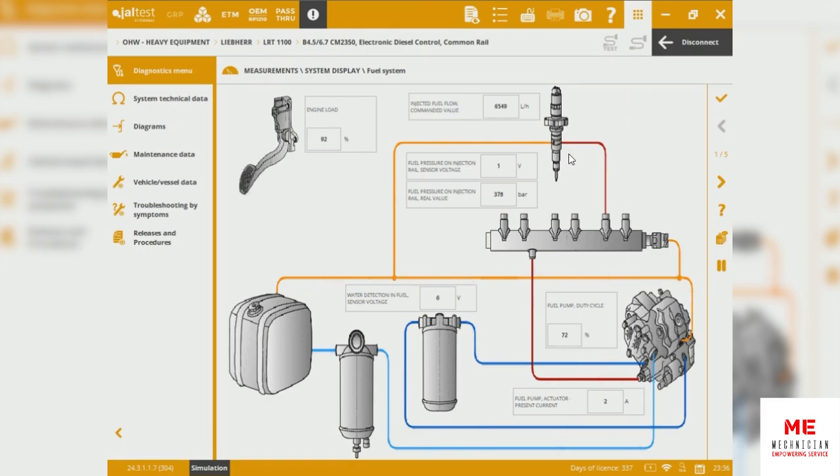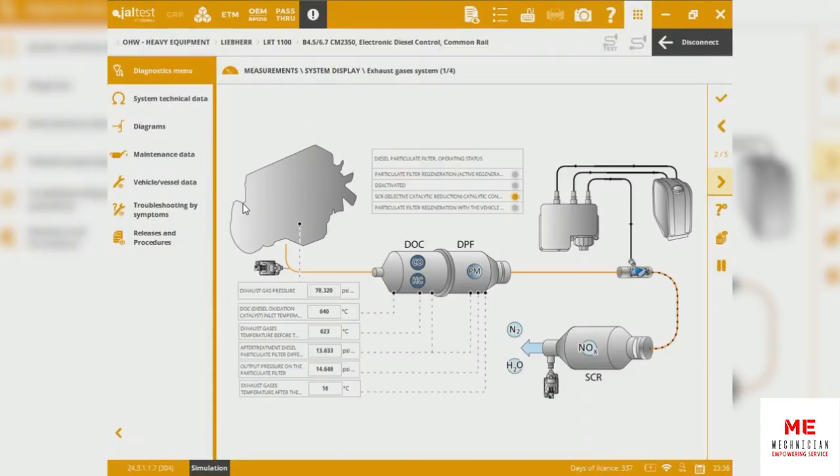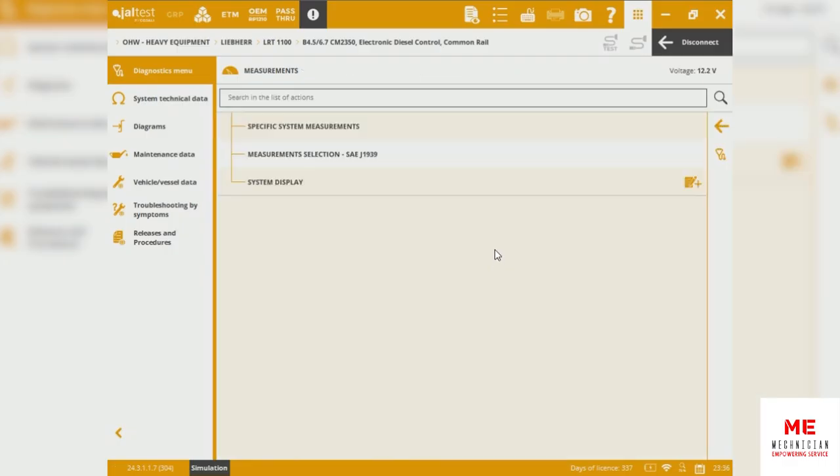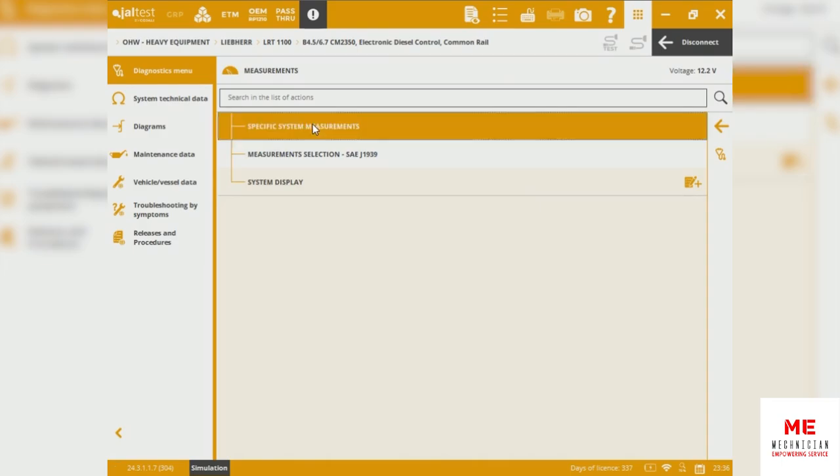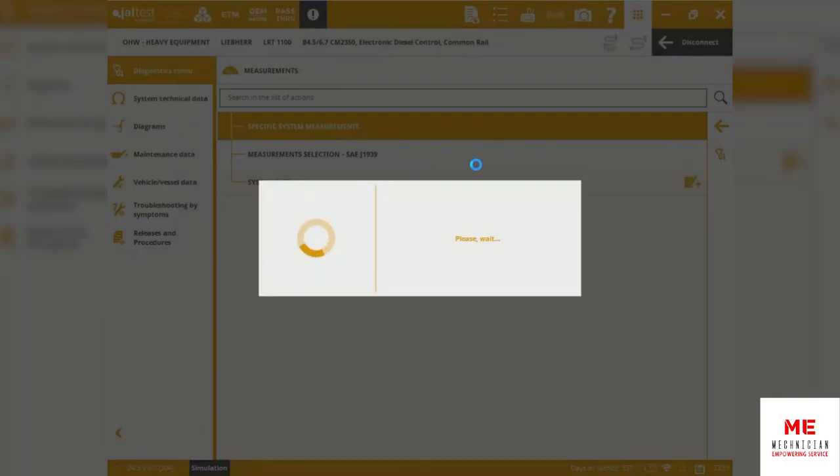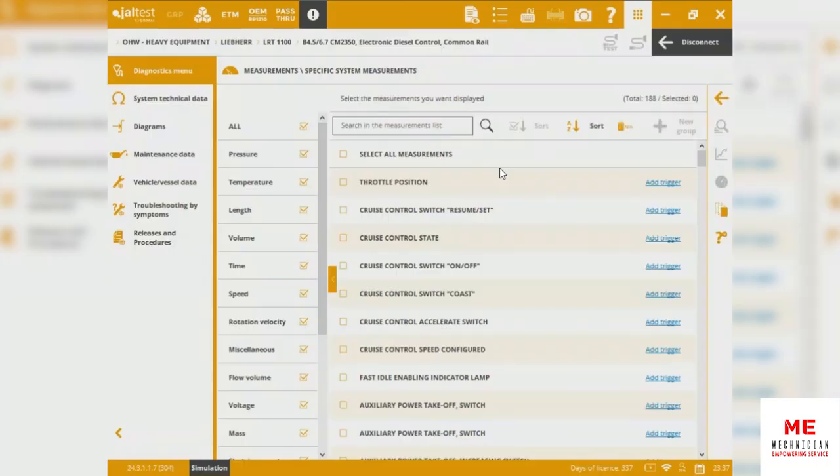We can see air mass flow of these injector state. And then going to the aftertreatment system, we can see these Tier 4 configurations that contain the diesel oxidation catalyst, particulate filters, DEF models and pumps. We've got SCR and ammonia components as well, injectors. We can see temperature, pressures, in which we're gonna be able to do road tests or even perform idle tests. We can also do a manual selection. We can just select specific systems, right, to be able to monitor all those measurements.